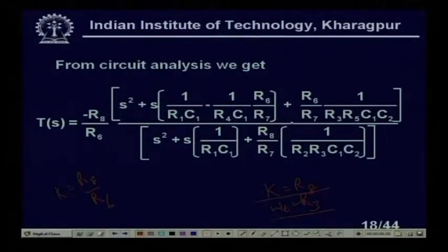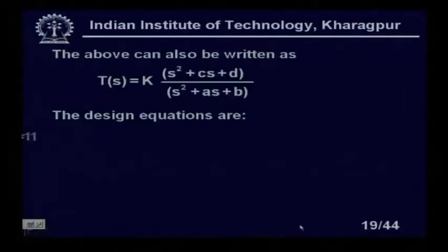So, that is the reason I am telling you that you have to maintain that particular sequence, otherwise there will be a problem. Now, you see, once I have chosen R3 to tune omega z, I am not using R3 anywhere to tune any other further elements. I will choose some other elements to tune omega p or q p like that, right. So, that is the case that I want to explain to you.